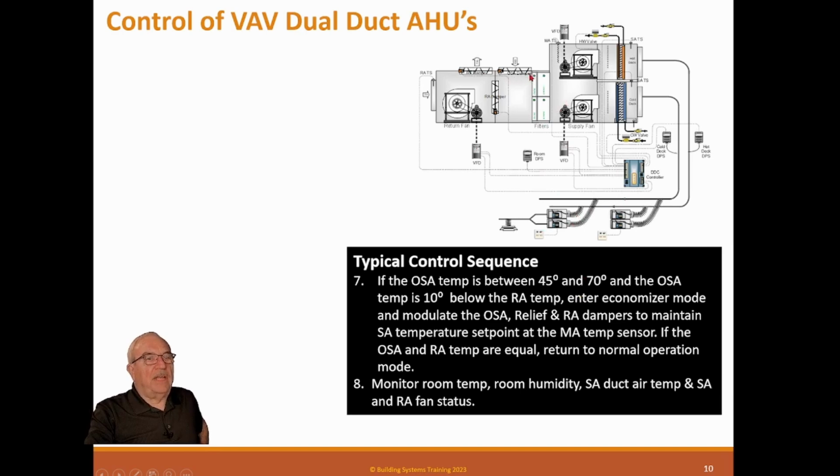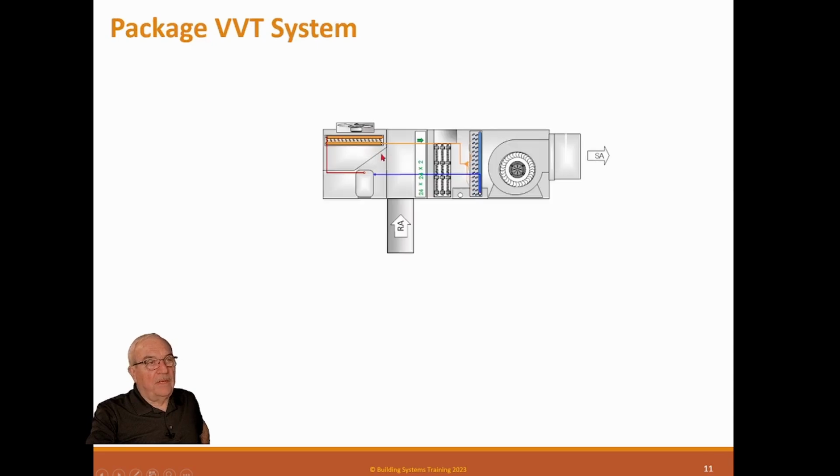Now this one here didn't have a minimum outside air damper. And the balance guys have little problems with this sometimes because these are called low leak dampers. Low leak doesn't mean no leak. They do leak. And sometimes, if the minimums are small, these dampers will leak almost enough for your minimum outside airflow. So it's good to have that little damper, that minimum flow outside air damper, in a unit. All right, now I'm going to switch gears and talk about a specialty one.